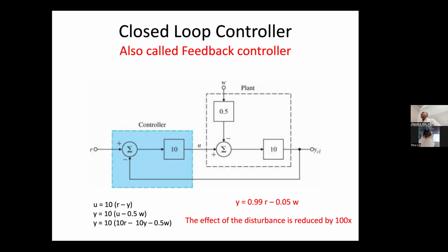The designer of the control system needs to know nothing about the system. This is the beauty. It is totally model free. It's like nothing. All you need to do is measure the error and then just act on trying to reduce it. It's like the beauty of gradient descent. Actually, Ben Recht has a post on connecting gradient descent and PID control in exactly this way. Okay. Now I'll do the slightly fancier version.